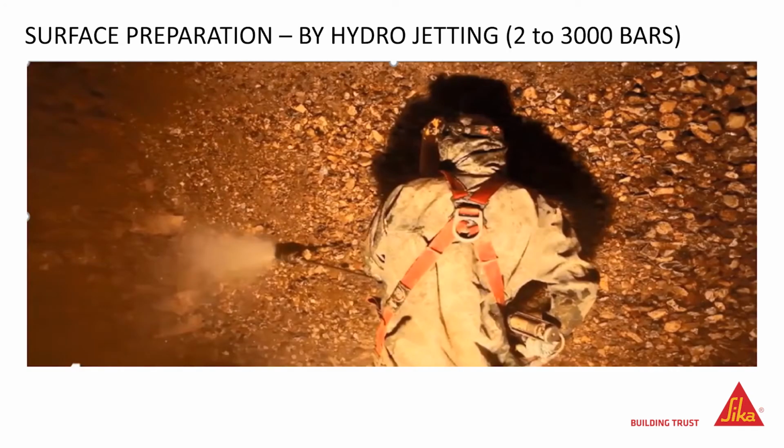Now let's have a look in the next few slides at the different steps for application, starting from the surface preparation. First, the damaged concrete needs to be removed. One of the best ways to remove damaged concrete is the use of hydrojetting. Other methods, like grit blasting, are also used.